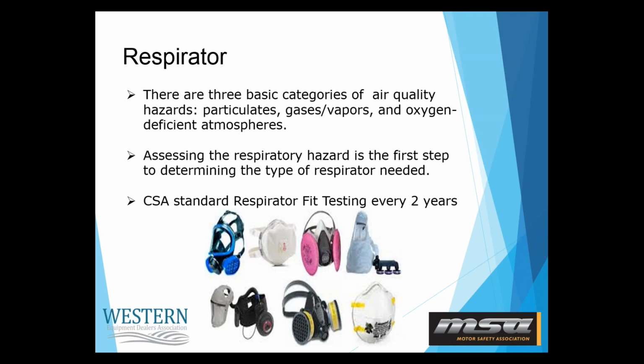And when we are looking at storing the respirators, so some of the other types of respirators with the cartridges on them, store them in a sealed plastic bag. This keeps the respirator clean, and it also helps keep the cartridges from being spent and using their useful life expectancy up. So store those in a sealed type of plastic bag. And pay attention to some of the replacement cartridges. They have service life indicators on them, which will tell you when they need replacement.